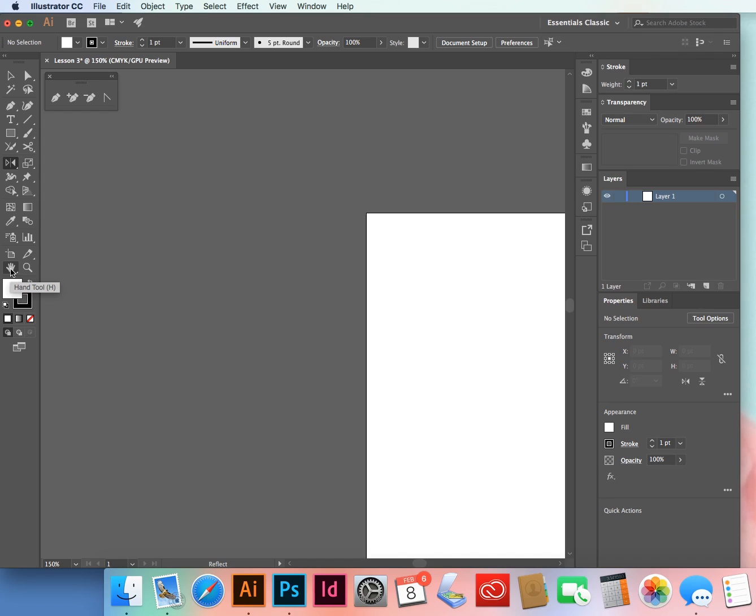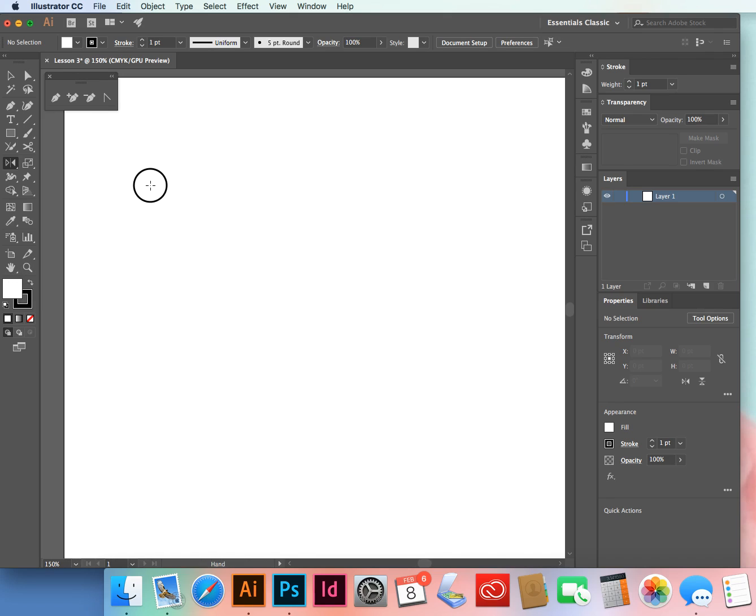The hand tool is easiest used, like I said, by holding down the space bar, and then you can sort of pull your image around. Our colours, we always have no colour when we're drawing, so you can either click on the little icon with the red line running through it or press the / key. So it's just drawing with black line, that way you can see what you're doing, still see the template.